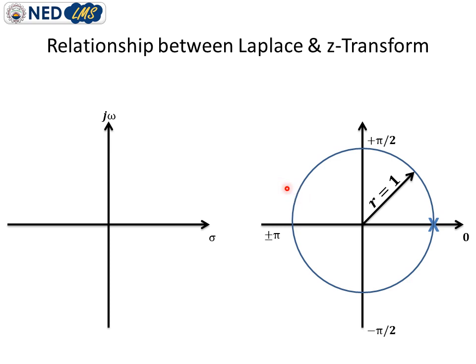then the system will become unstable. So this solid line is basically the unit circle of radius 1, and all the poles that lie within this region will make the system stable. So this region is basically the stable region in Z transform.